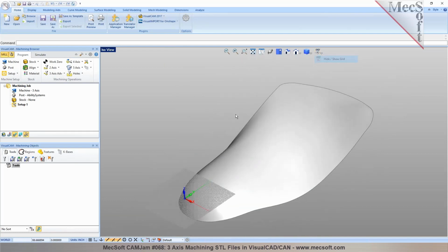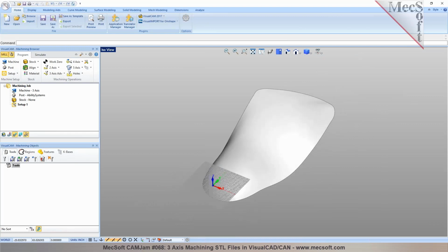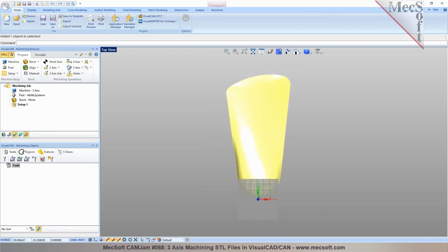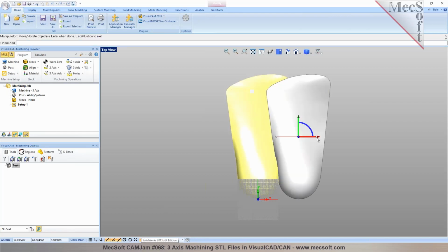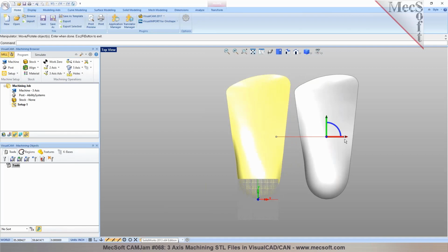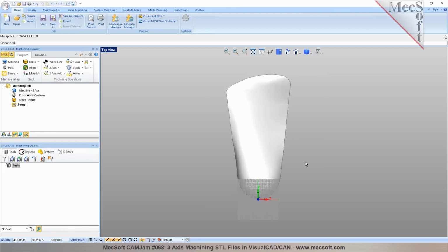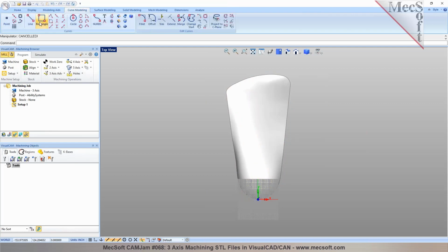If you want to do multiple of these parts, you can import multiple of them into the same workspace, and you can graphically or manually move them over. You can select it and use the graphical manipulator tool, where you can easily move them freeform if you need to. You can drag and drop into a workspace. You can define your sheet, where you can draw the size of your sheet. You can say a rectangle and specify the sheet extent.